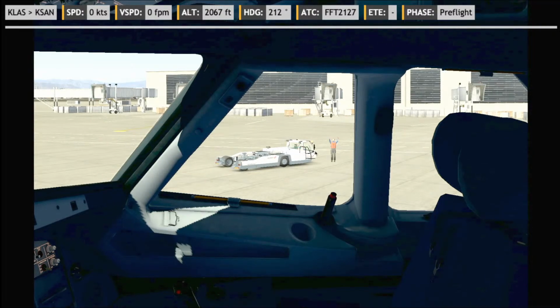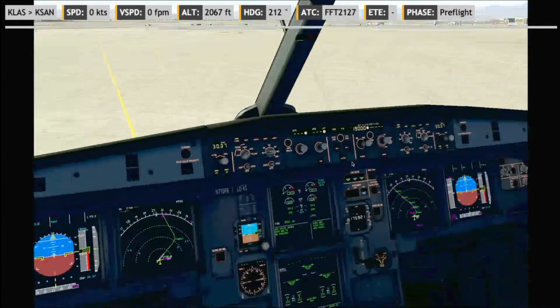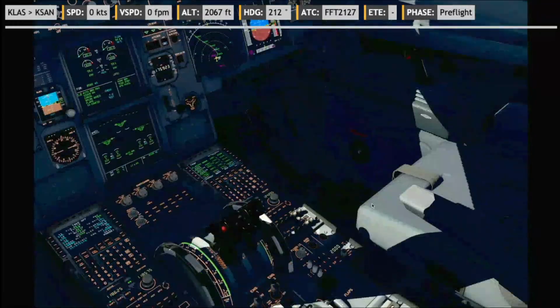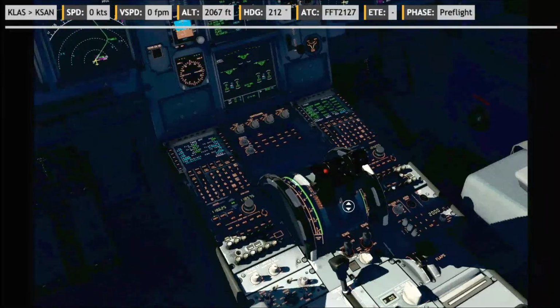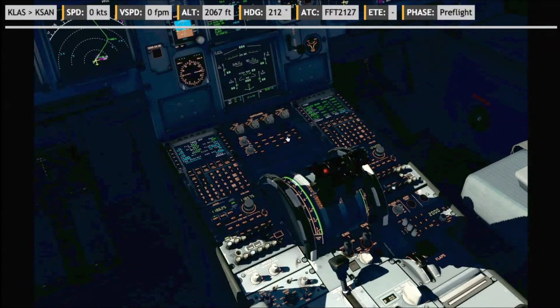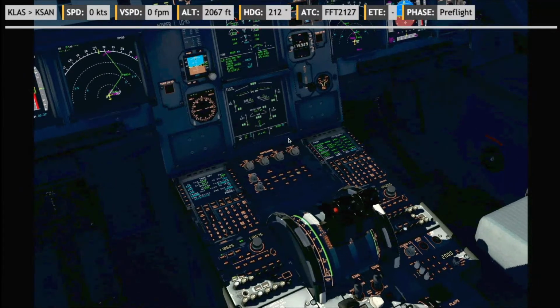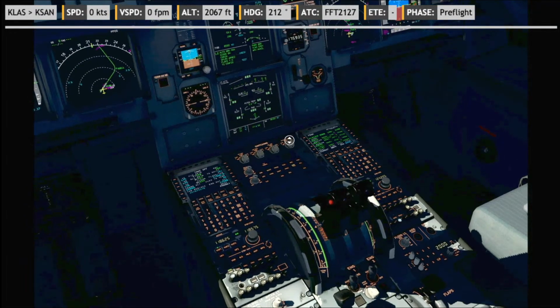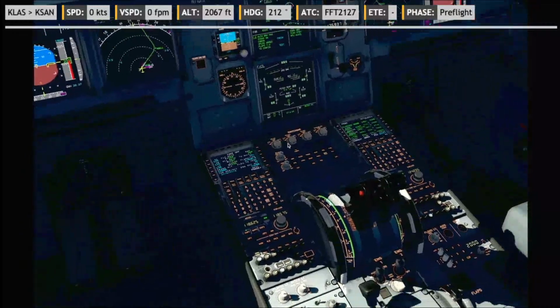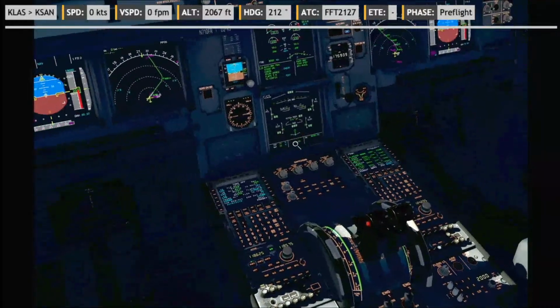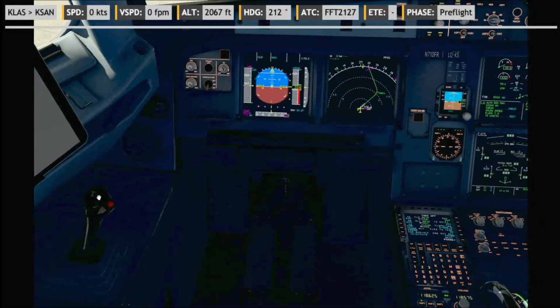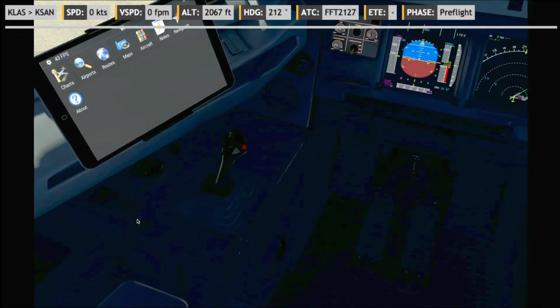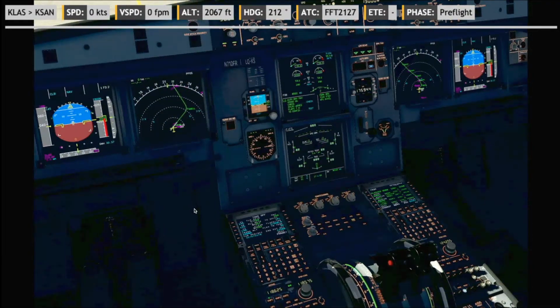There it is. Great. So we'll go flaps 2 for departure. Selected. Flight control check. Select flight control here. Full forward. Checked. Aft. Checked. Left. Checked. Right. Checked. Rudder left and rudder right. Checked. Now, it doesn't show up here, but that's only because I have the nose wheel tiller bound to my roll axis on there.